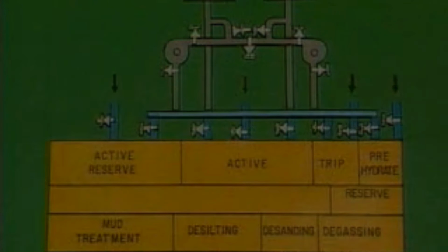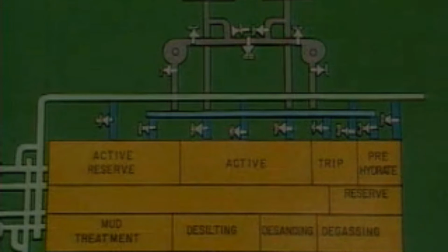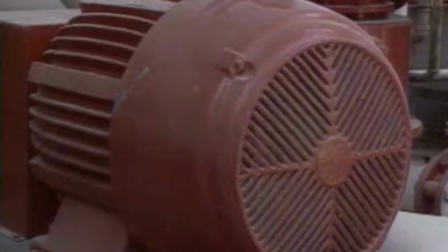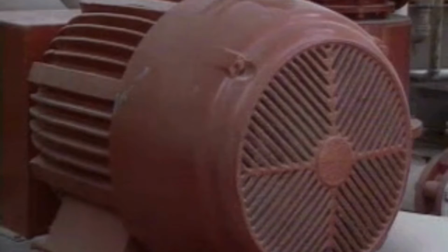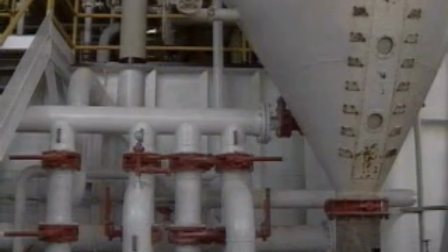The other valve from each tank connects to another suction manifold that we'll call the transfer manifold, and it ties directly to two other low-pressure centrifugal pumps called mud mixing pumps. These mud mixing pumps output to a series of pipes and valves that allow you to direct the fluids to either the mud jets in the mixing room or directly to any one of the pits.